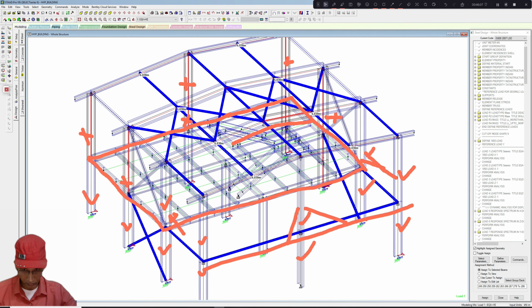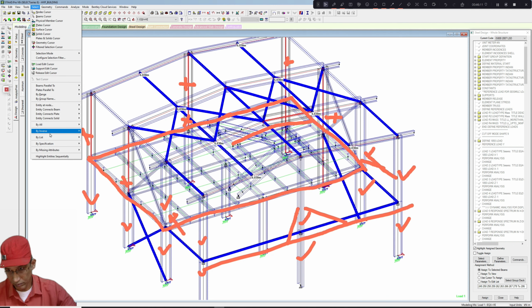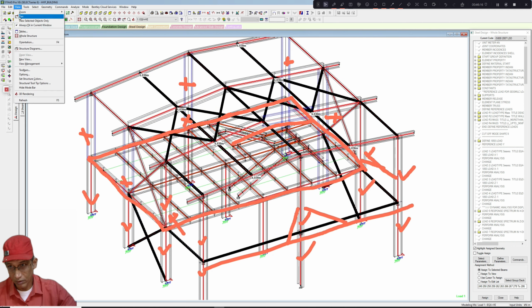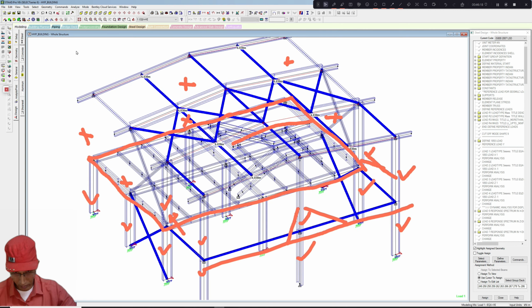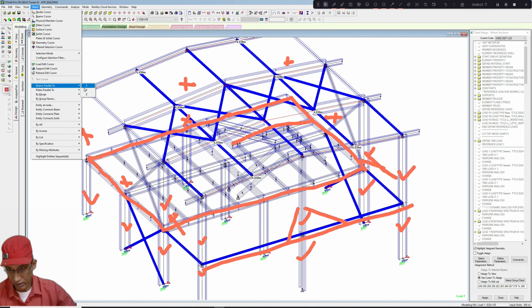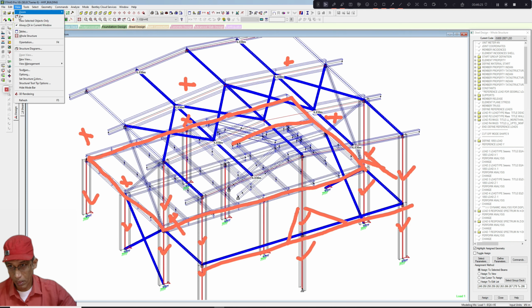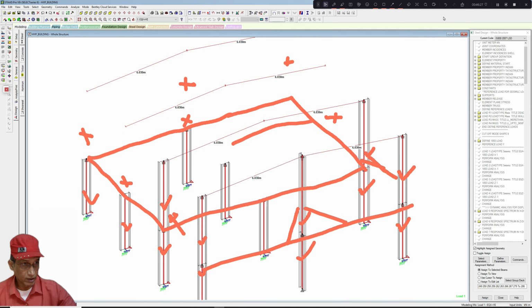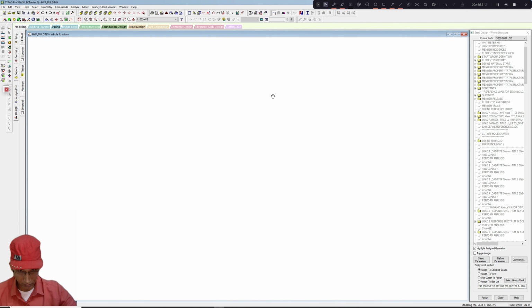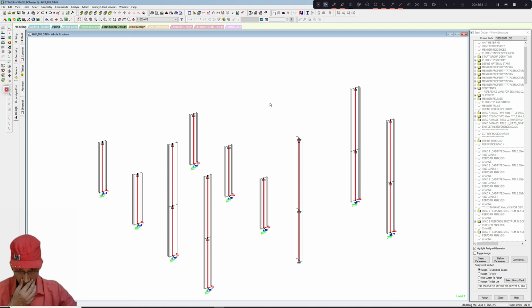So now select by inverse. View selected object. Now select beam parallel to Y. Clear the drawing. Clear the dimensions. Now all these columns we can have flange braces, but not for this interior column.